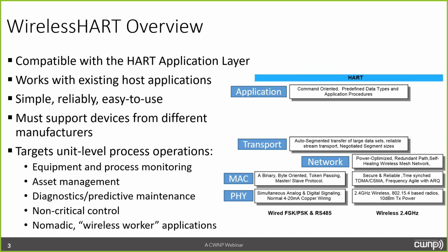The HART application layer, the commands for HART are the same commands that are used in WirelessHART. So that application layer is supported. And that means it works with existing HART developed applications as long as they don't do something odd and actually care about the physical layer or the MAC layer.